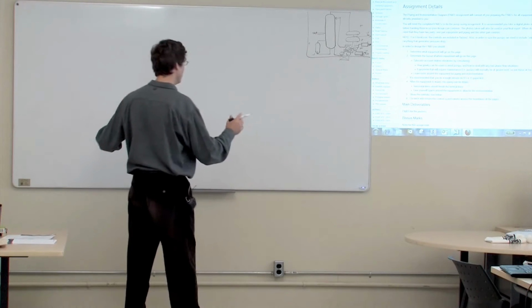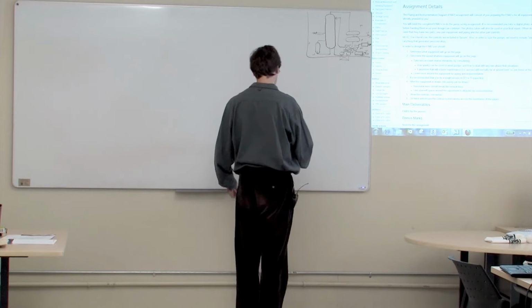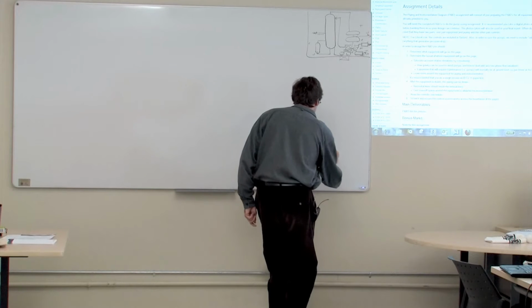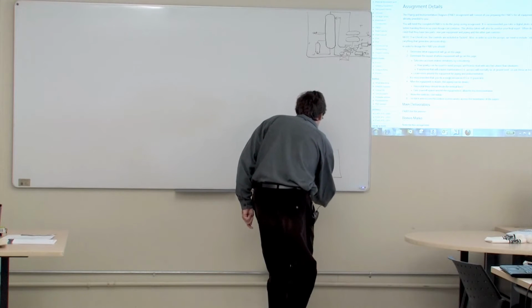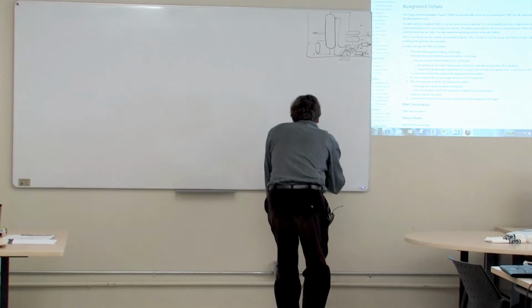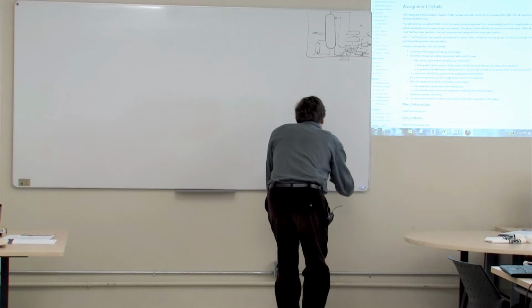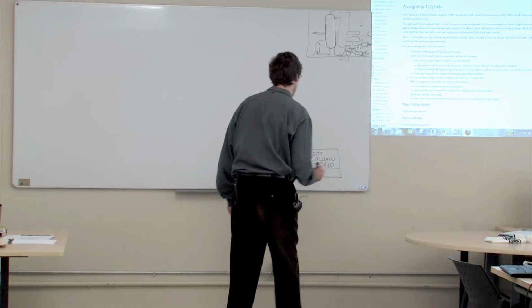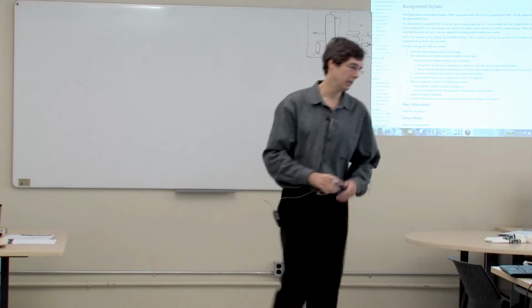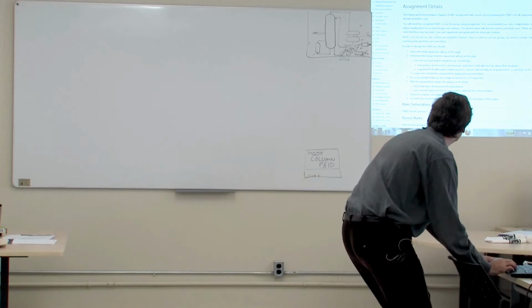And the version that I'm going to draw, well, I guess one thing we should do is put a title block on. And just so that I can keep things nice and large, I'm going to draw the title block over here. And this is going to be the methanol column P&ID. And you should put your name and your date and the sheet number or the drawing number. What drawing number is this going to be? We do need to give it a name, a number.